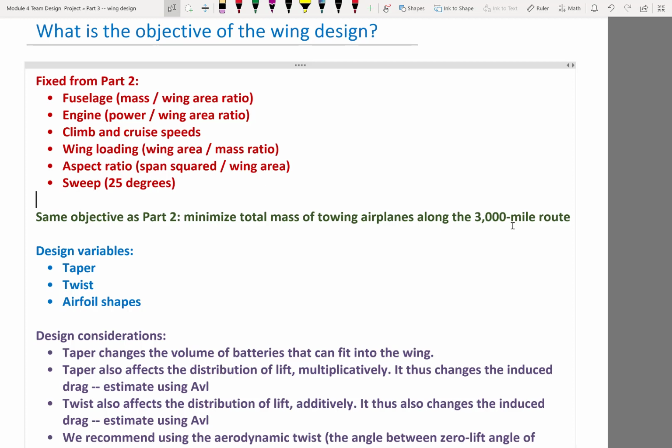Considering that a higher lift coefficient in the center and a lower coefficient towards the tip is also aerodynamically more efficient from an induced drag point of view, right? This might be beneficial. I mean, this is the original 737 design anyway, so you might want to start from the taper ratio of the 737 wing and see if you can change it to make it even better.